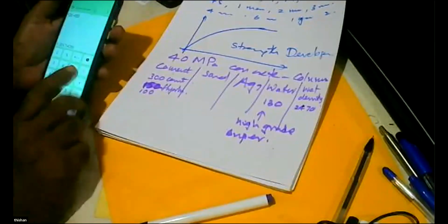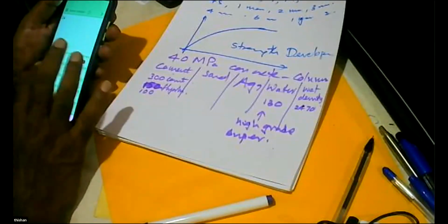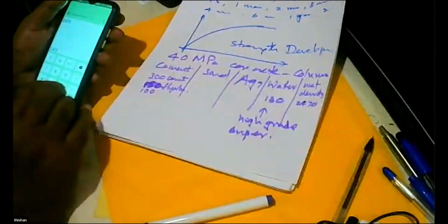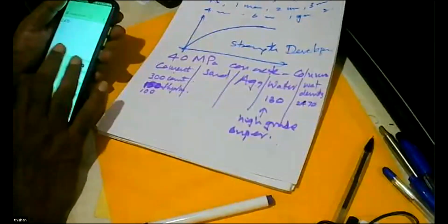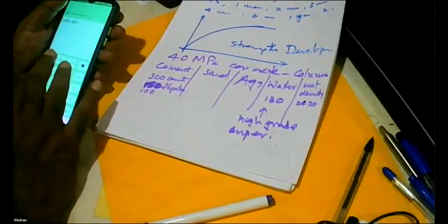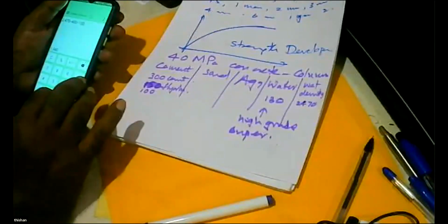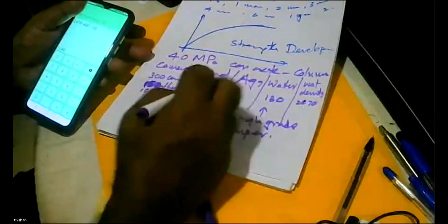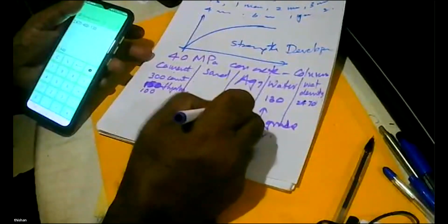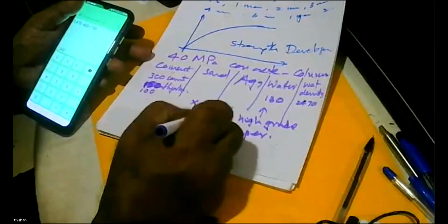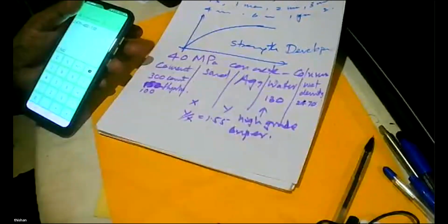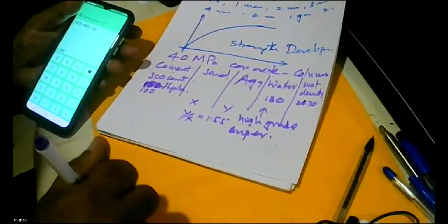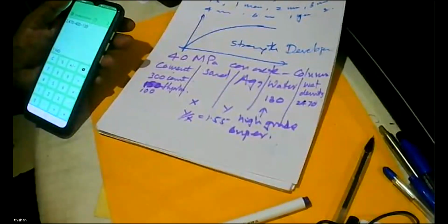Now I'm going to look at numbers. 2470 minus 400 minus 130. Now this is in a column, so I have to pump. So I'm going to use a y over x ratio of 1.5. I like to get high strength also, so I don't like to use too much sand. I like a little less sand, but at the same time I'm a little restricted.